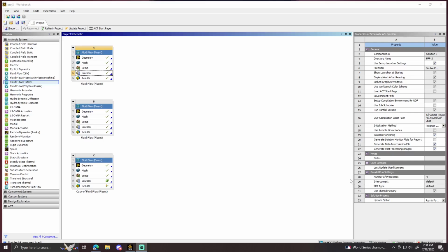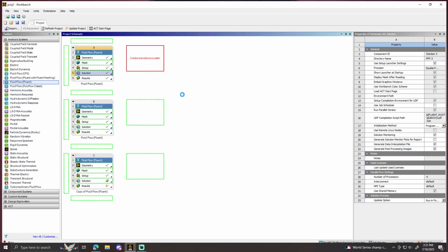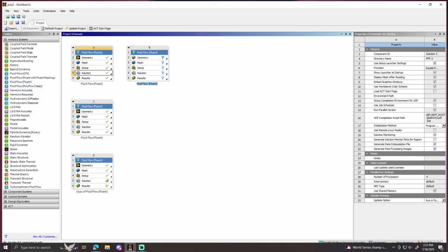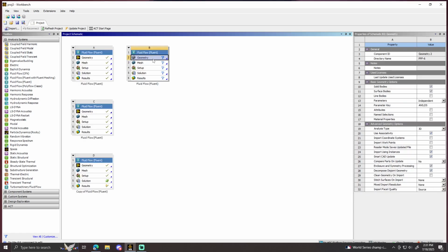Hello, my name is Thomas, and this is my first video for Project 3. I'm going to be doing Inviscid Flow. So first, I'm going to create my system, right-click on Geometry, New Design Modeler.